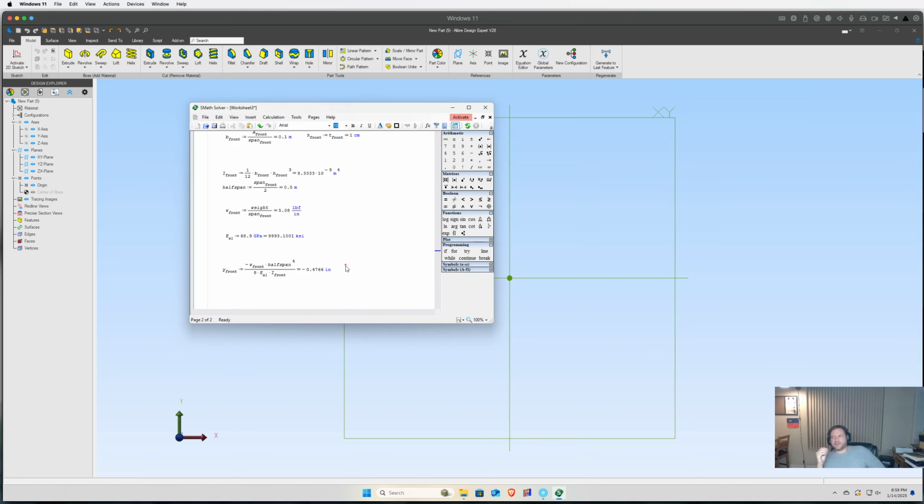And this is something you have to think about with any kind of problem. You can't just say half an inch of deflection is small. Well, if this was near a gap that was only a 1/4 inch gap or so, this would close that gap. So your model, your idea of reality is just not sufficient to understand that. And now your flow is sensitive to your deflection. That comes up in heat exchanger design and things like that, or any kind of internal flow where a small deflection could actually greatly change your whole flow.